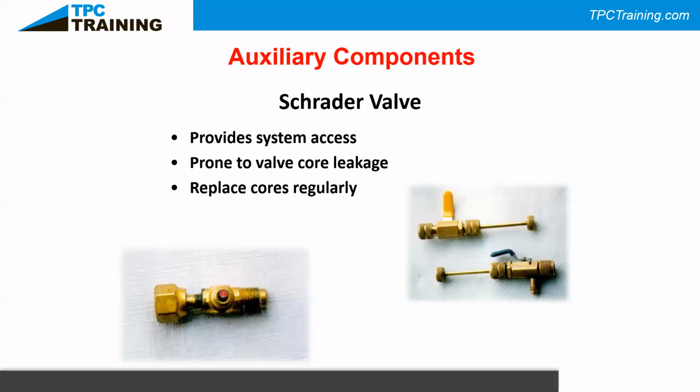If you remove one of these Schraders, you should not put it back into the system. Once it's got refrigerant exposed to it, the gasket expands, and then you're putting the gasket back into a smaller opening, and it'll rip and tear that gasket. Keeping the caps on here is very crucial because the caps are going to help seal up the system in the event that that Schrader is slightly leaking refrigerant out from the time that we're putting the gauges on till the time we come back to service the unit.